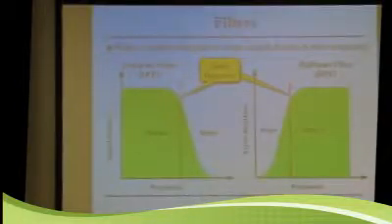Well, that can occur, but it doesn't occur naturally. Normally what you get is slopes here. And what you have is how much attenuation occurs at so many kilohertz away from the cutoff frequency. So anyway, that's one of the things we talk about, capacitors and inductors, and that's one of the things we do. We make a low pass filter that would pass the 3.5 megahertz and attenuate anything above that.